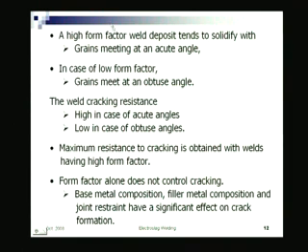Well, so that is one aspect. Also, it does not mean that form factor alone controls the cracking, definitely not. Base metal composition, filler metal composition, joint restraints, all those other aspects are there. But what it means is, this is one of the important aspects, the form factor, which needs to be controlled such that I have a higher value of it, such that I achieve a higher resistance to cracking.